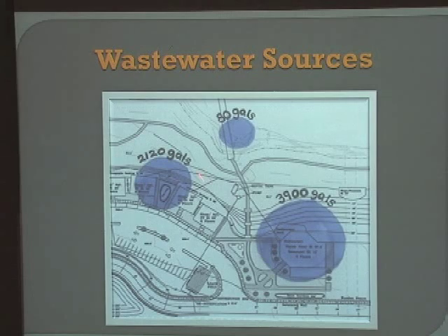Next, we have the residences and shop areas. We figured out that was going to be about 2,120 gallons a day. We based that upon a total of 8 bedrooms with 115 gallons a day per bedroom, 2 small food shops at about 500 gallons a day, and also 2 non-food shops at around, I believe it was 100 gallons a day.